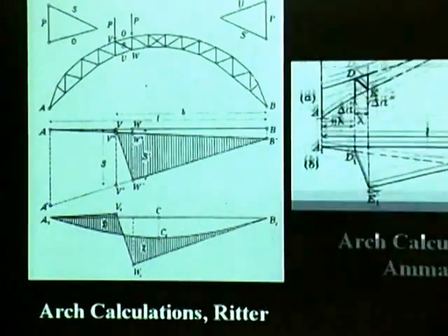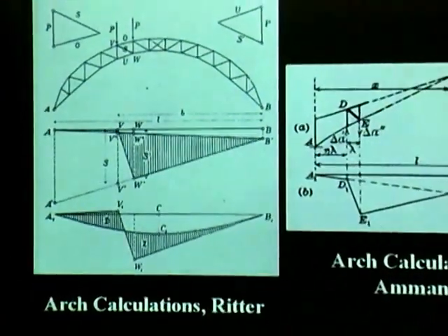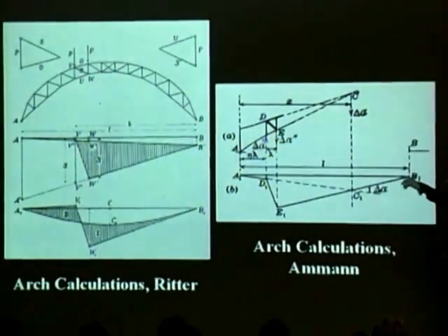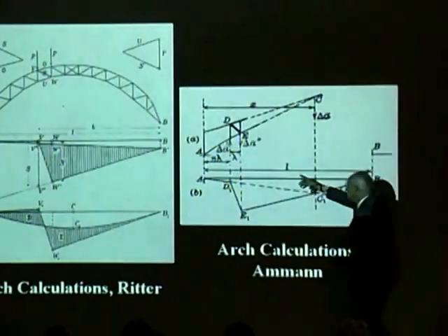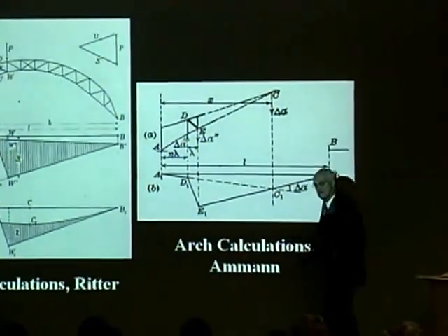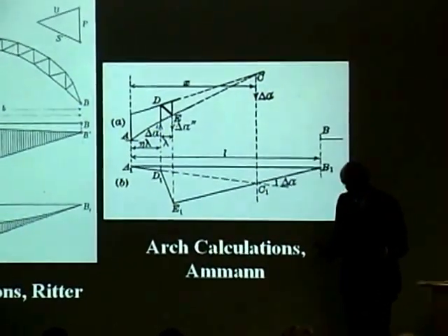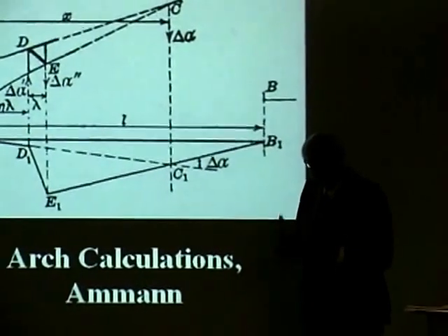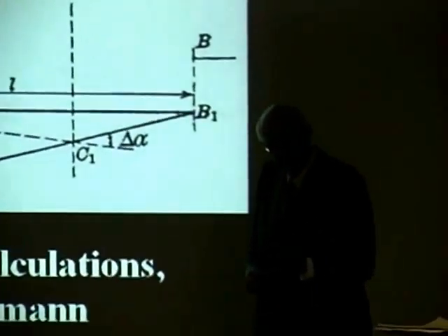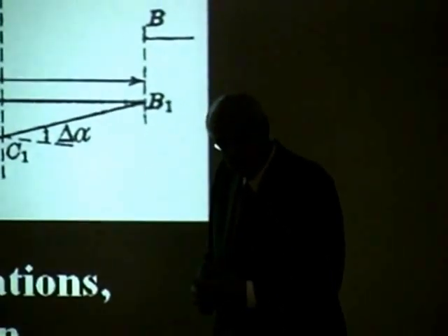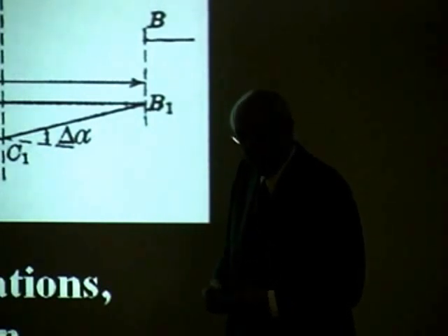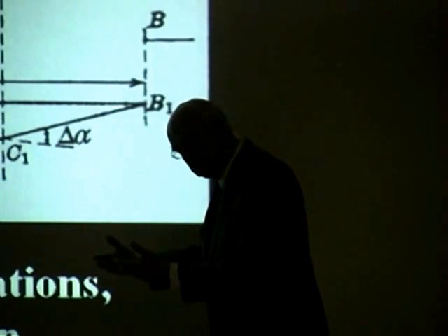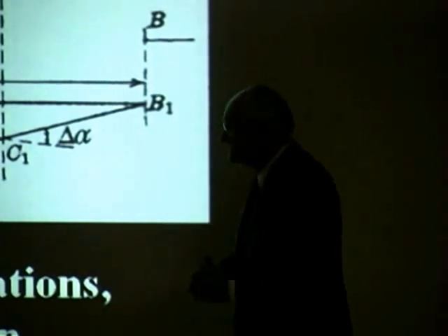And next slide, these are calculations made by Amann, and you see it's the same calculation of the stresses in a piece up in here, how he arrives at that piece through this graphic statics, which is a way of visualizing the form as you are making an analysis. Something that was invented essentially in the school in Switzerland by Ritter's teacher, and Ritter taught that to his students, a combination of visualization and analysis.